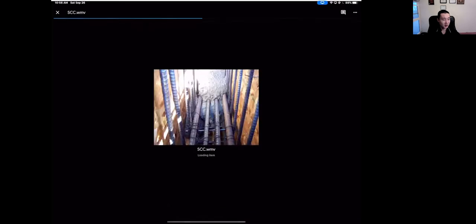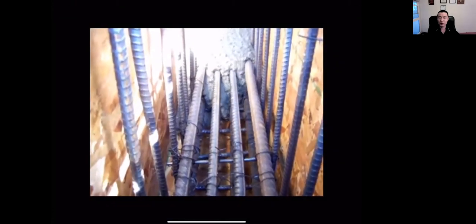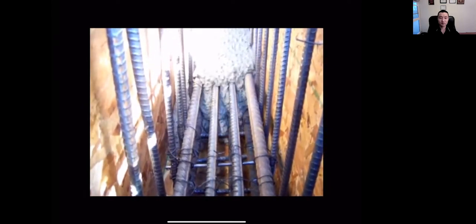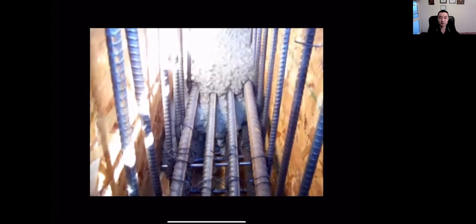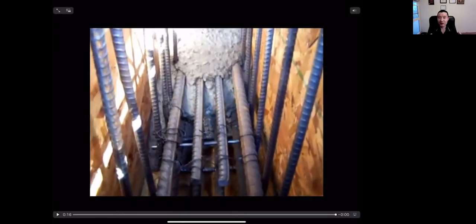All right, so this is a video of SCC flowing. We can use a pump and it flows under its own weight and fills every corner of the formwork. Even though the rebar is very dense, it can still go around the rebar and achieve very good bonding.